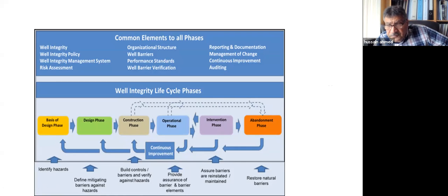You have done some kind of change, a packer has been changed, for example. You have done well logging. You have installed an ESP, electrical submersible pump. You have installed a gas lift. These are the interventions during the life of the wellbore. We need to know them because these affect the integrity as well.